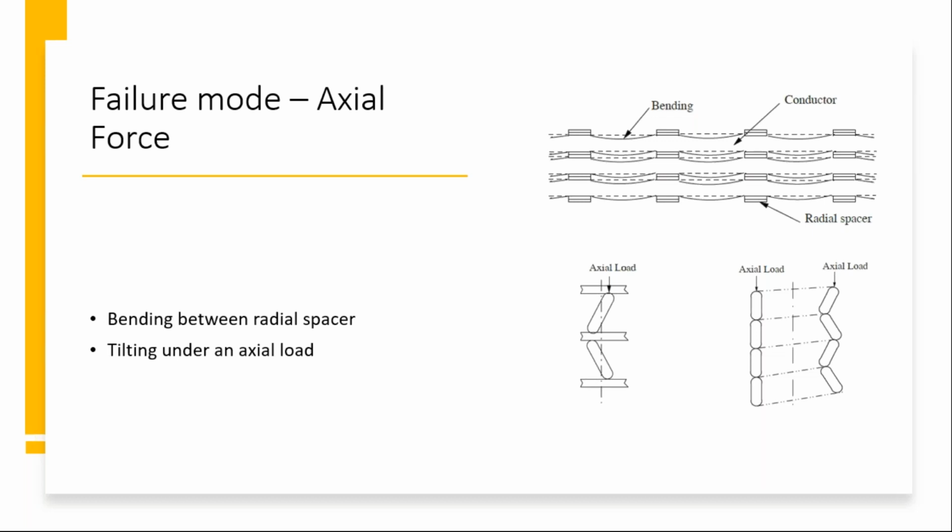But when we go for CTC conductor with bonding, the strength increases quite a bit, because we have epoxy on the conductor which gets cured at 120 degrees Celsius, and which makes the conductor as one conductor for the short circuit condition.